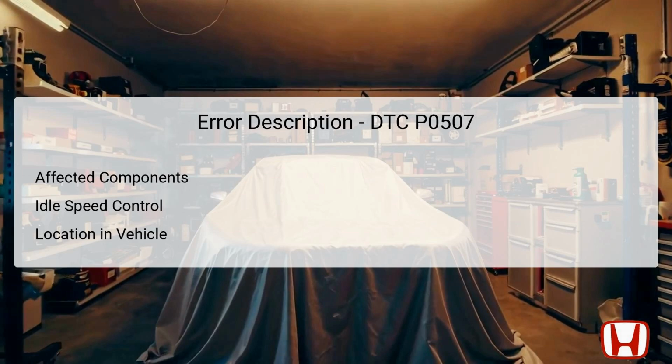If these components are not functioning optimally, or if there are any air leaks in the intake manifold or throttle body, the PCM may receive inaccurate readings, consequently triggering the P0507 code. Identifying and addressing issues within these components is crucial for rectifying idle speed discrepancies.